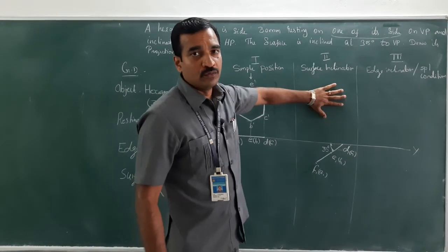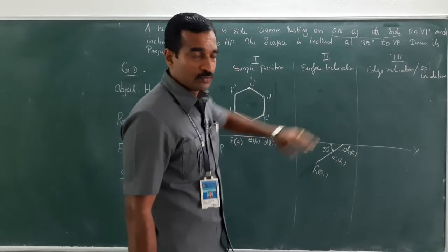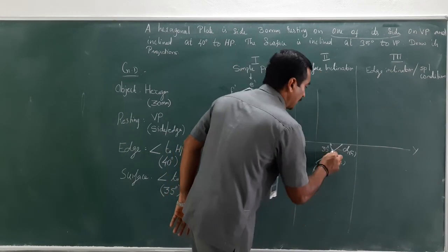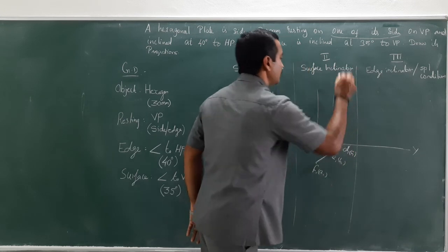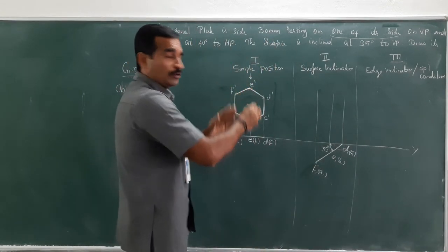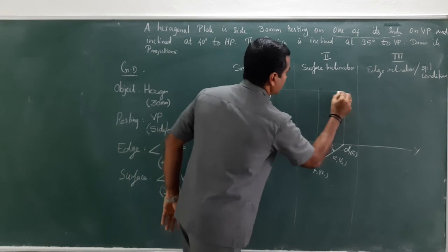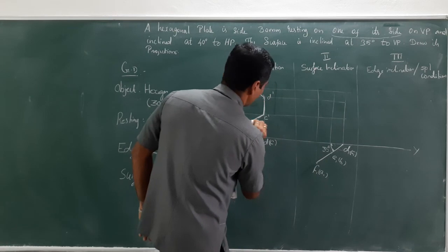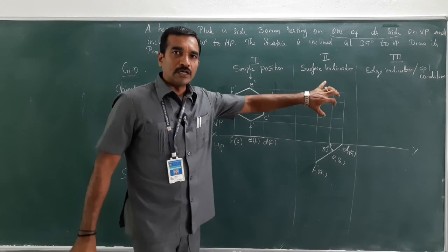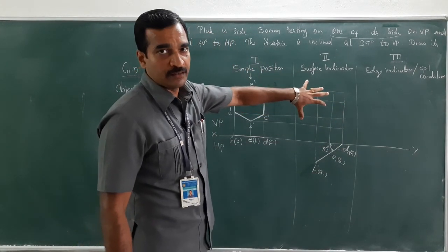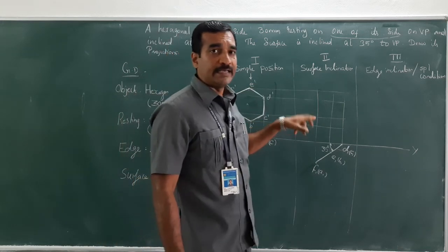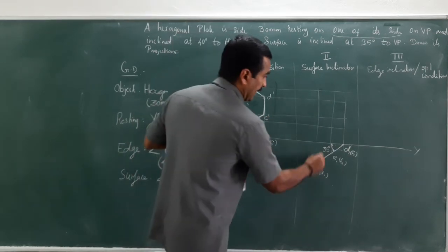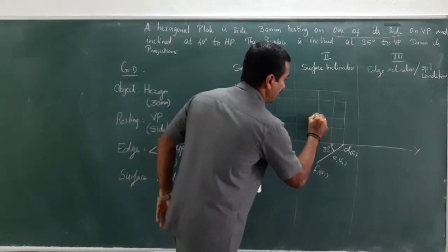What about its front view? In order to get the front view, you will have to extend these projectors vertically upwards, and from the front view, you will have to draw the horizontal projectors. Now, I will have to do the mapping or graphing work here, for which we will see the intersection points, the horizontal and vertical of A intersecting here. This could be A1 dash.